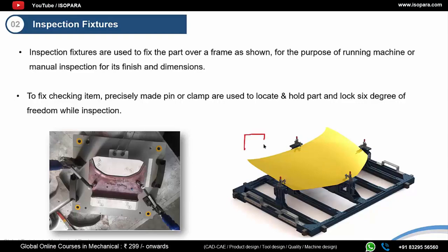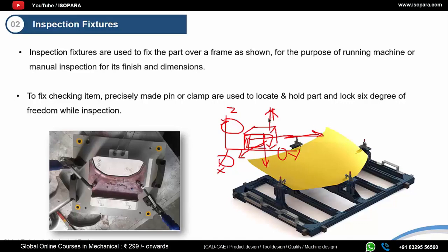Any part can be in a Cartesian system. Let's say this is a cube, and every Cartesian system has 3 axes, the x, y and z. So this cube can be translated along x, y or z, or it can be rotated along the x-axis, y-axis and z-axis. In total we could say 12 degrees of freedom if you count positive y and negative y, positive z, negative z, and so on, but here you can only say 6.